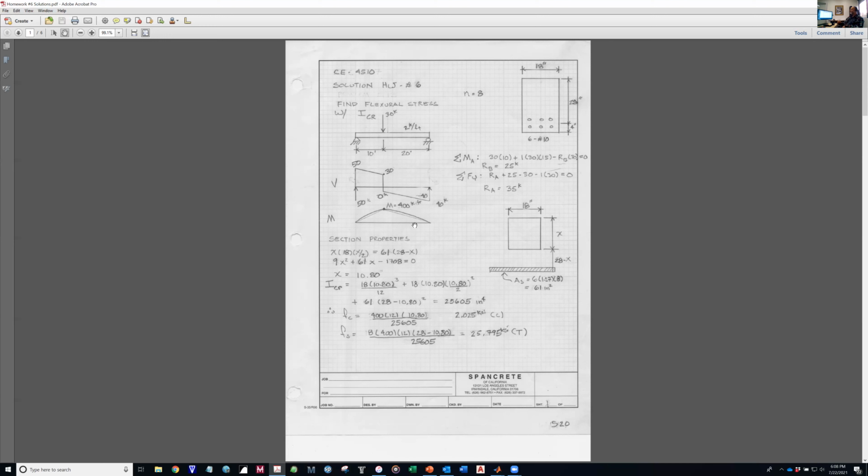Well, there's a u in there. That tells you you have to use factored loads. For the column designs that we just started working through, the end game is for you to tell me that phi Pn is greater than Pu. The u, again, tells you it has to be factored loads.